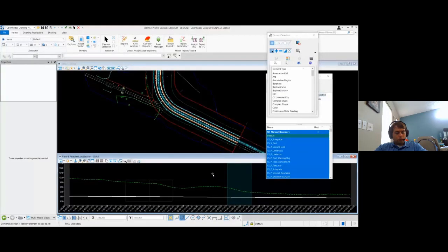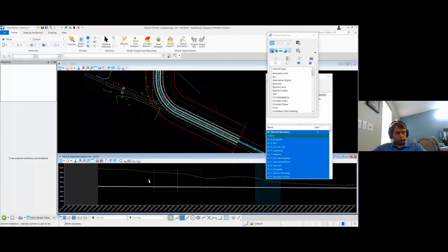I will say that I have been running into some inconsistencies, or I haven't been able to track it down just yet. But what I found is that I consistently get the level display to work when I cut my sheets before I do a 3D cut or attaching all profile views. When I attach the profile views or do a 3D cut and then I cut my sheets, I've had sporadic results. It's always around these two levels, basically never being able to stay on.